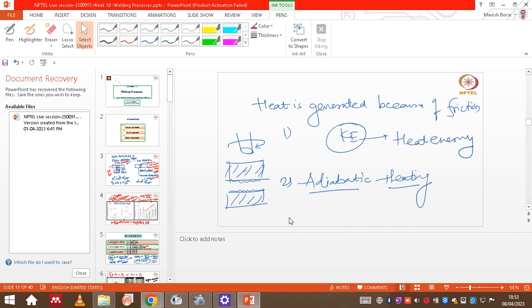So there won't be any problem because of that, because sigma y is very less. Yield stress, right? If the metal is significantly softened at lower temperature, and in friction welding or friction stir welding the temperature is more than even 0.4 or 0.5 of melting point, then it will be sufficient.